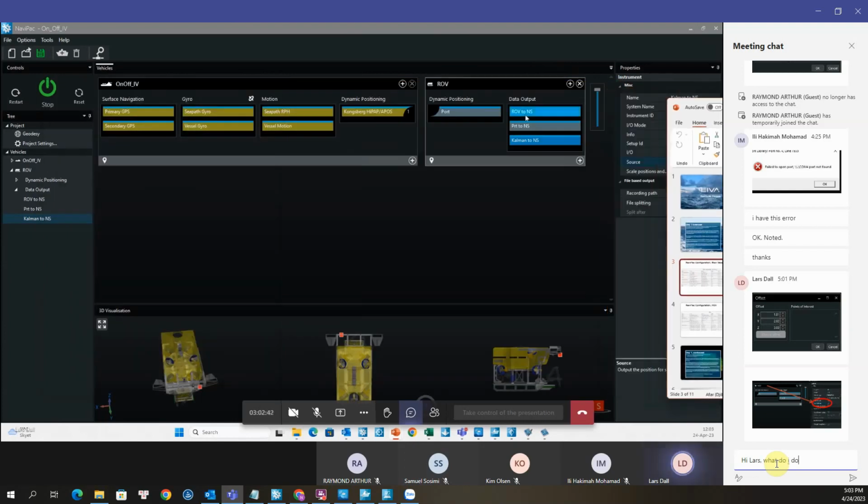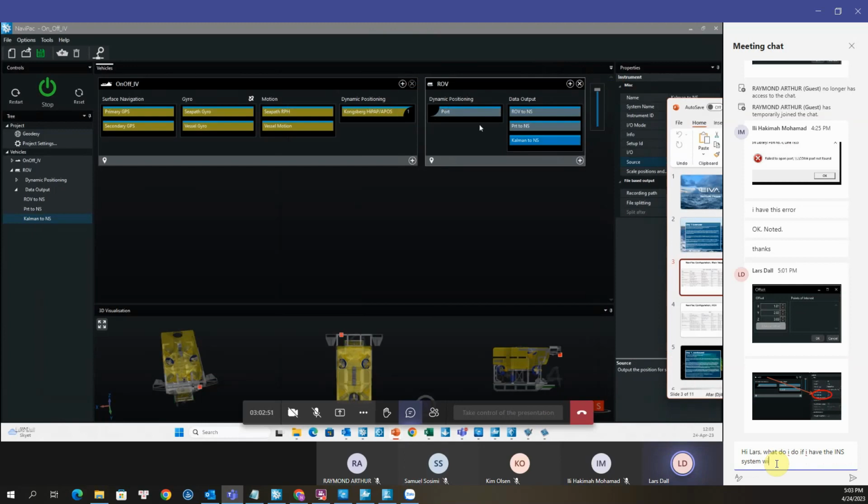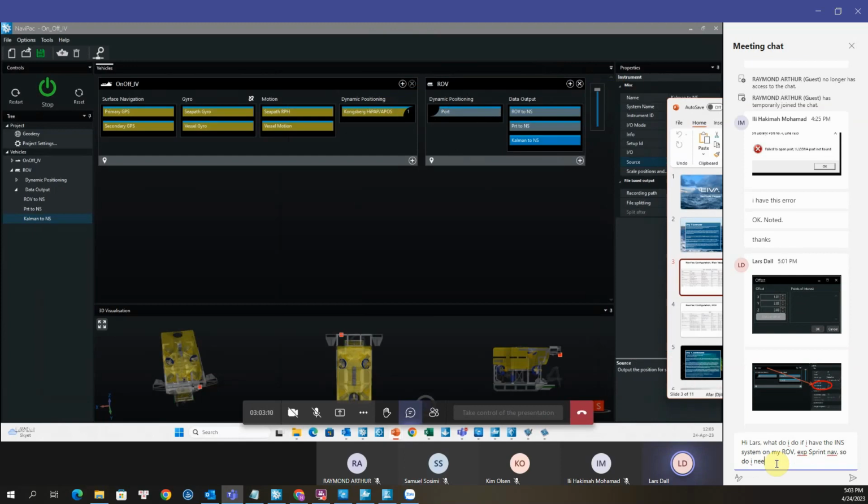The second transponder is going to be related to Kongsberg. You just press the plus once again, then you get a Kongsberg transponder. Once you have the Sonadyne, then it will say 0 here, and then you put your cursor there and press the plus and add another transponder to the RV object so that you have 3 transponders, 2 related to the Kongsberg, 1 to the Sonadyne.